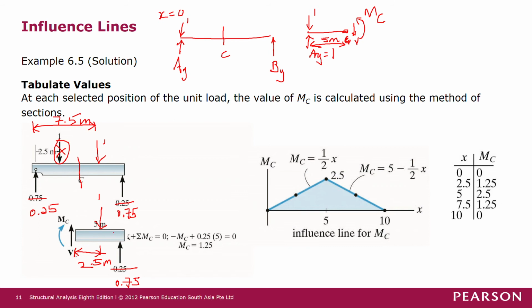So even if we use this free body diagram, we may also solve for the bending moment MC, but there's another step further that we have to do because of this 1 unit force here. So let's look at how we sum moment here and get the solution.